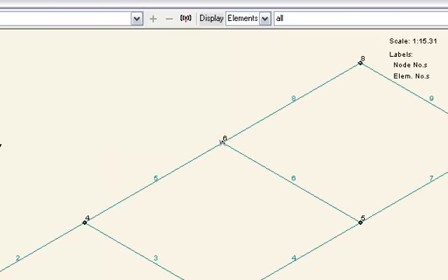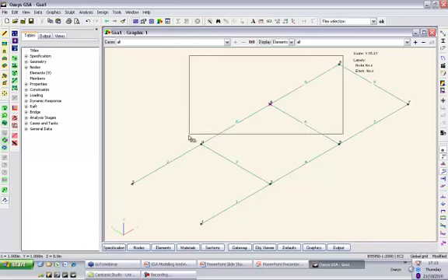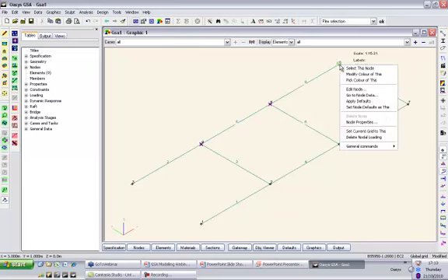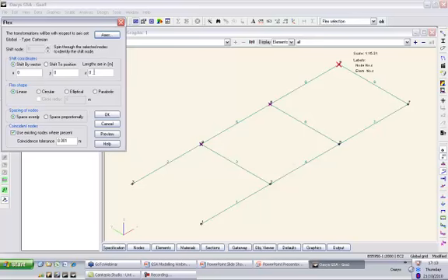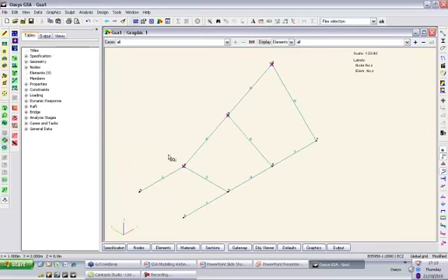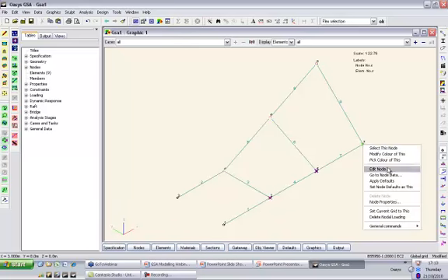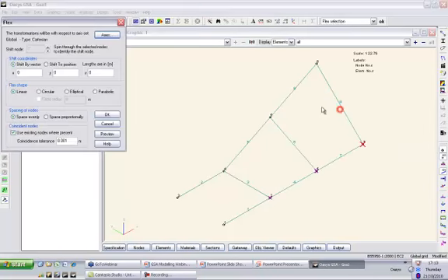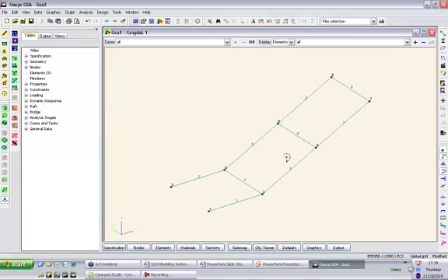And in fact, I'll just show you. If I go back to this model here, which is going to become a staircase, well, ramp. If I right click on that end node and flex that node, I'll do a linear flex, move it up 1 meter, and lo and behold, the ramp forms. I'll do the same on that end. And voila, we have a slope.